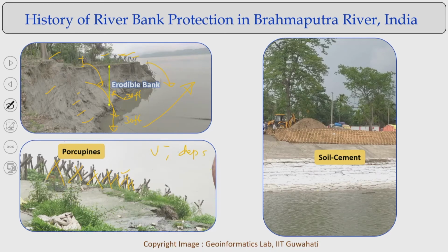The siltation will start, and that siltation can facilitate the river diverting from that location. So, we have been putting this type of smaller structure on the banks of the Brahmaputra, expecting that the velocity near the bank will decrease, initiate sediment deposition, and because of this deposition the river can change its course and move away from where it is.